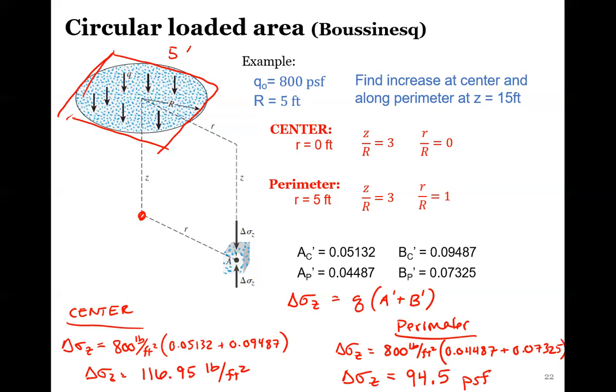So again, if you have low loading and you're pretty sure that the site conditions are pretty consistent, you're confident of the soils that are there, you're confident that the structural engineer knows what type of loading there is and it's not going to deviate too much, then this type of analysis is okay. If you have some settlement or some issues, it's not going to be the end of the world.